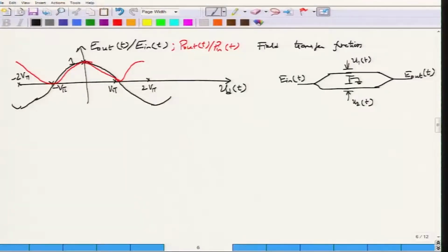If you recall from the last module where we stopped discussion on the Mach-Zehnder modulator, we derived the input and output electric fields for this modulator. The structure of the modulator at its very simplest sense, we have not looked into the physics yet, would consist of the input waveguide through which we couple light from the source such as a laser, and then this light is split into two paths or two arms.